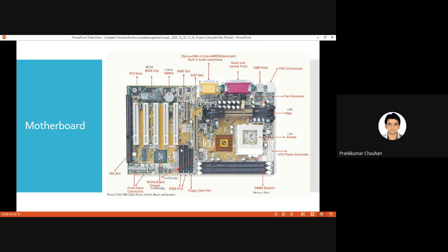See, if you are attaching a hard disk, then how the hard disk sends a signal to your motherboard and the motherboard replies to the hard disk signal will be controlled by the South Bridge. As well, if you are inserting a USB pen drive in this USB port, besides the USB port we also have an HDMI port. If you are connecting any external devices by using external ports, that will also be managed by the South Bridge. If you are inserting any TV tuner card in PCI slots, that card will also be managed by the South Bridge. Clear?